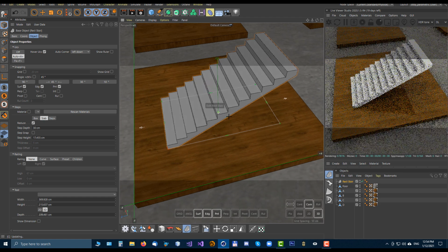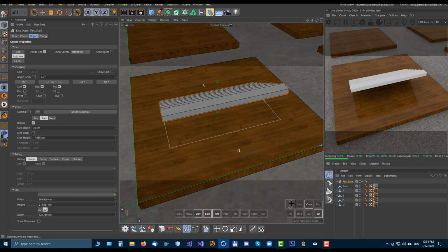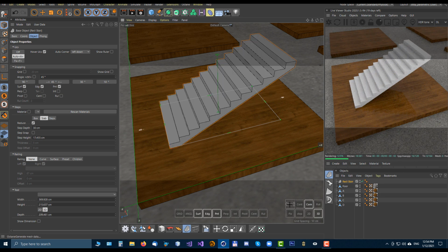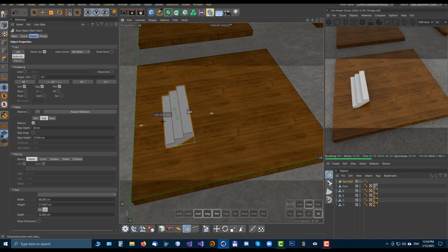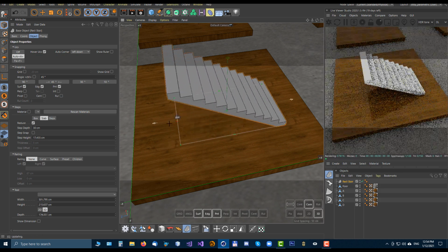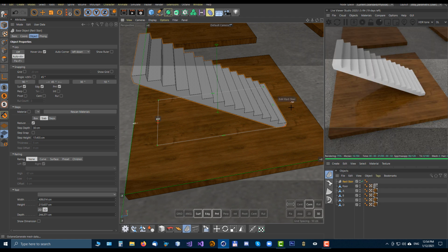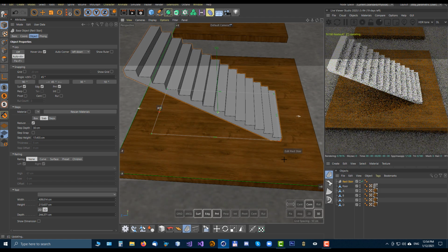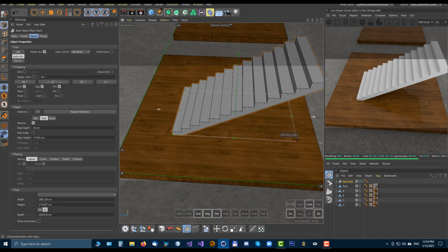And for the manipulation, you can use this orientation button to flip the stair orientation from left to right or up to left. You can very easily drag the left handle to the right and back, and this way you can change orientation. Also very useful is the fix button, same as in other tools.